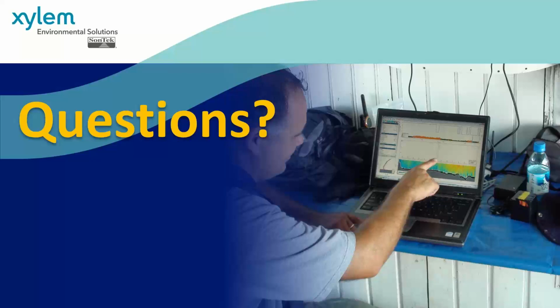Network RTK assumes that some other agency, whether a government agency or a private agency, has set up a base station for you already. You usually sign up for some sort of subscription service to tap into their base station. In that way, that base station acts like the normal RTK base station that you would normally use. So in terms of network RTK in the field, as long as you have some way to access the base station, usually we just use a hotspot.